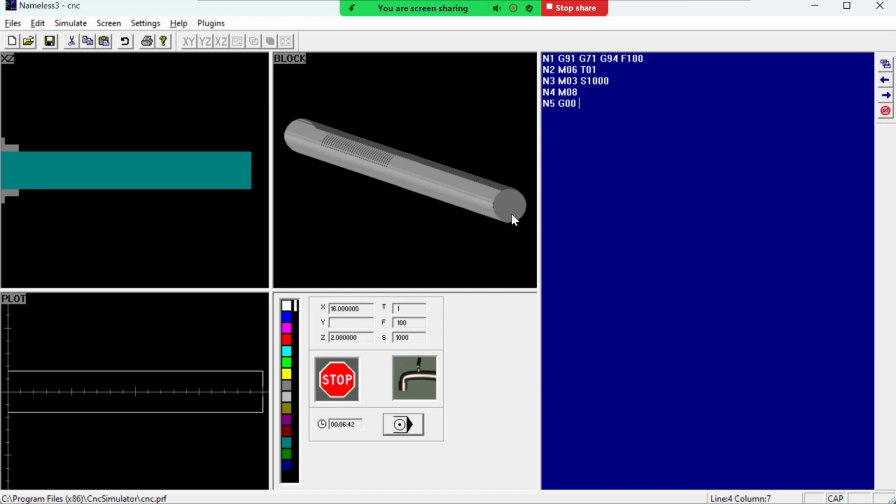So the X coordinate and Z coordinate will only change. The Y coordinate doesn't change here. So I'll type X 32 and then Z2. So wherever the tooltip is located before, this code will allow it to be relocated at this point. Now because the tooltip is situated at this point, in the next line of code, we will actually mention where to relocate the tooltip to.